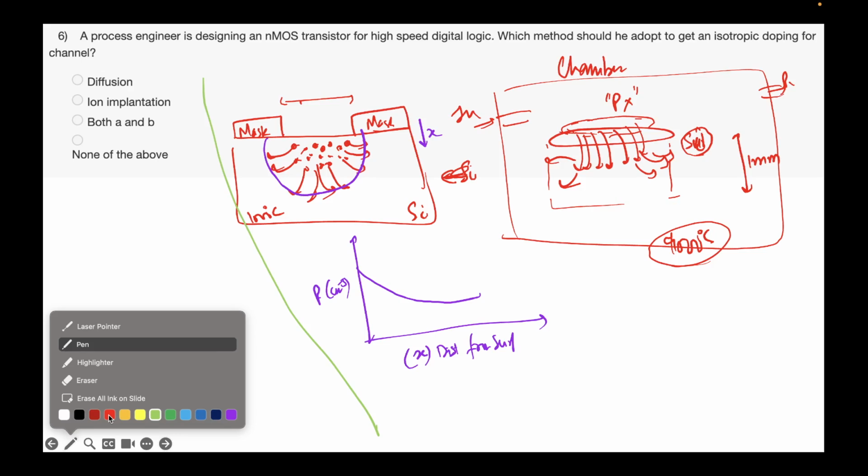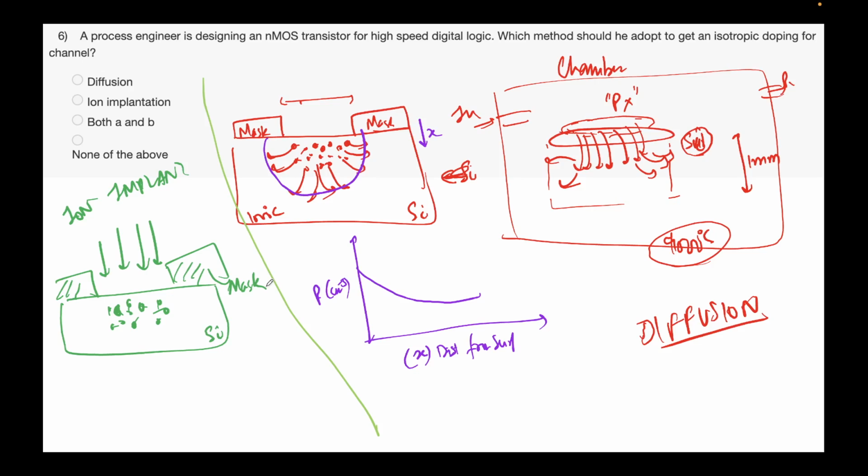We have silicon and we have these masks. So this is mask and this is silicon. What's going to happen is you are going to bombard some phosphorus ions, and they'll get embedded. Simple as that. That's how it works. It damages, so in order to activate them properly, you anneal it, so it will have some diffusion. Yes, true. When you anneal, this means to reduce the damage and diffuse them, but it will not have such a prominent effect. Its profile might look something like this.